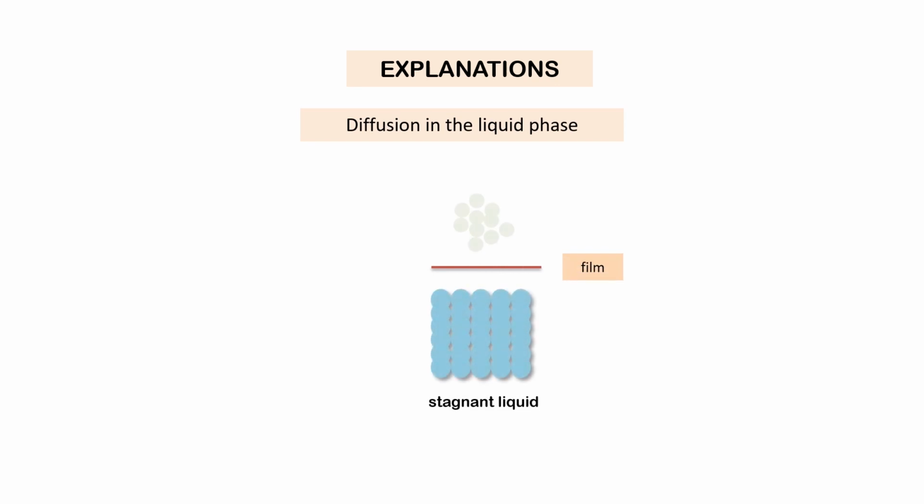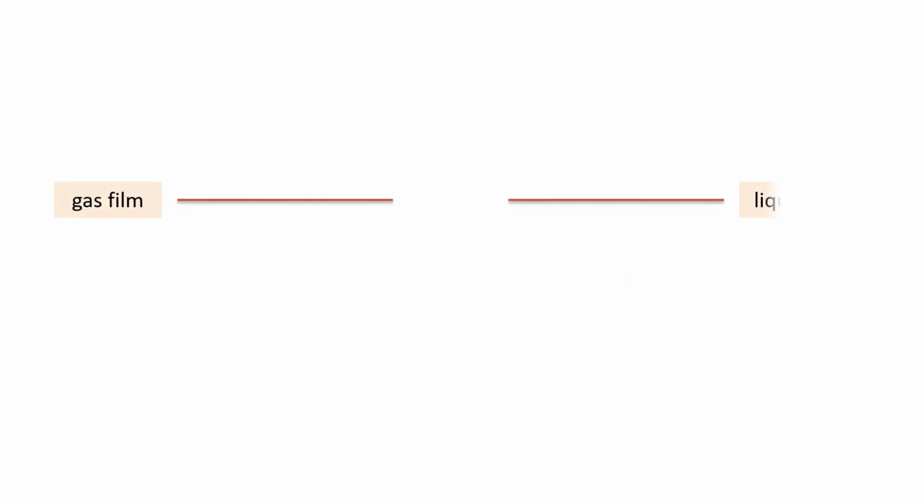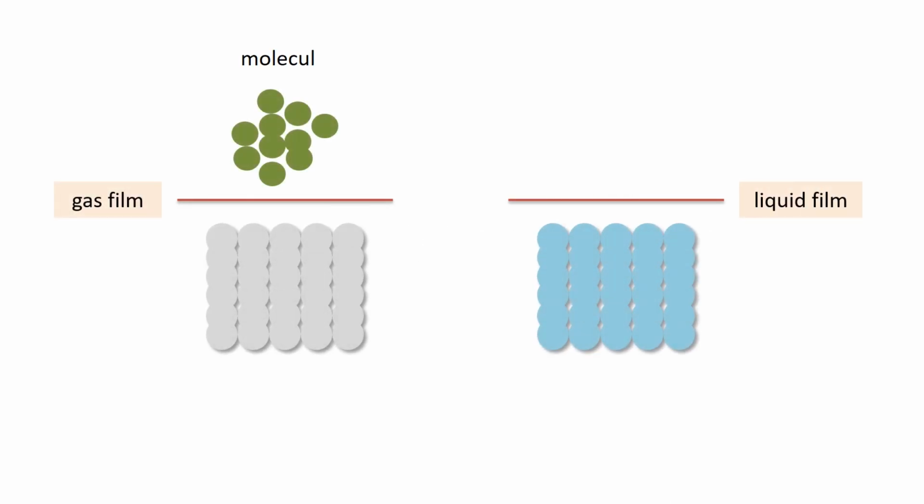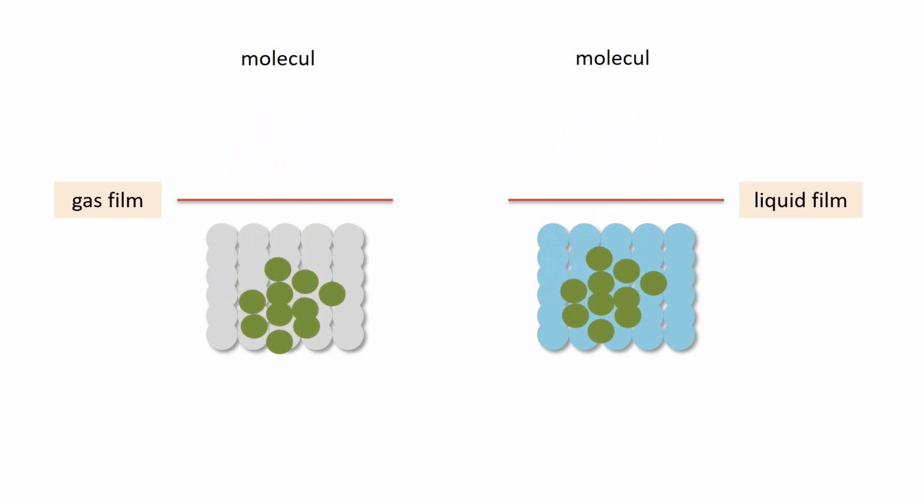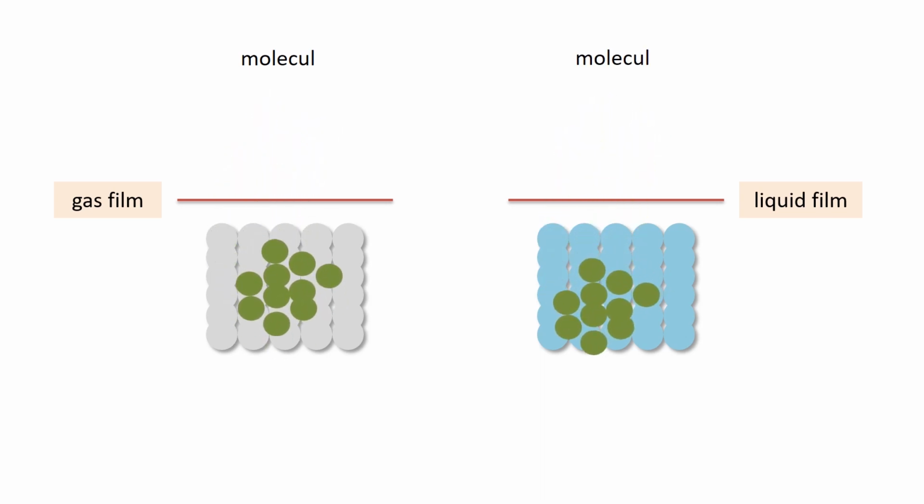Diffusion in the liquid phase is much slower than in gases, and mixtures of liquids may take a long time to reach equilibrium unless agitated. In steady-state processes of absorption, the rate of transfer of material through the gas will be the same as that through the liquid film.